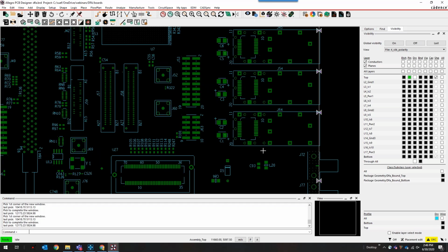So the OrCAD professional product abides by the DFA rules, but you will not get the bubbles with the OrCAD products. You need to have Allegro PCB Designer or above in order to get them. So that could be why you might not be getting them in your tools. But if you have your spacing spreadsheet set up, it should be showing the bubbles automatically in Allegro.